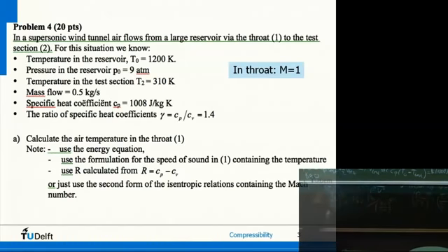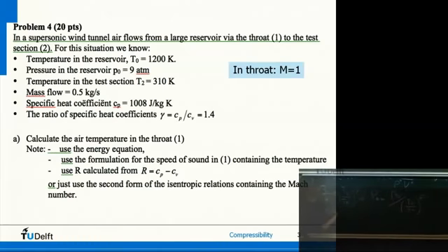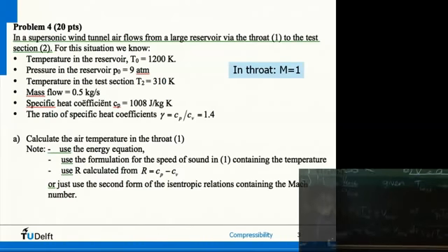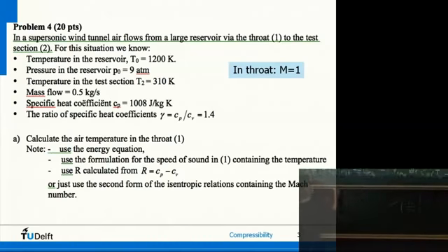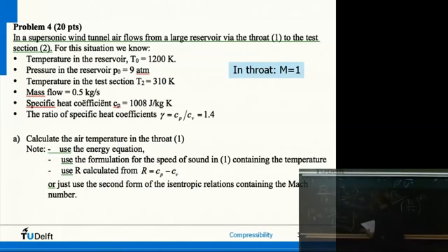And that's not so interesting. So rho star is rho 0, which we just computed, 2.64, divided by T0, which was given, 1200. T star we computed at some point, right? Yeah, 1000 Kelvin. So this is A to the power 1 over gamma minus 1, so that is 1.4 minus 1. And then we find 1.674 kilograms per meters to the third. Oops, are we done now?